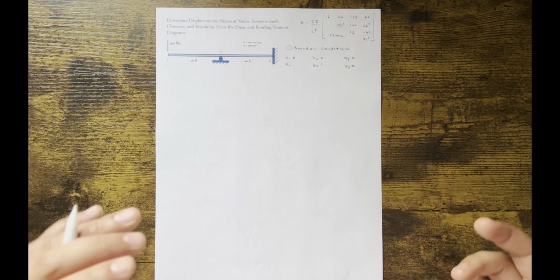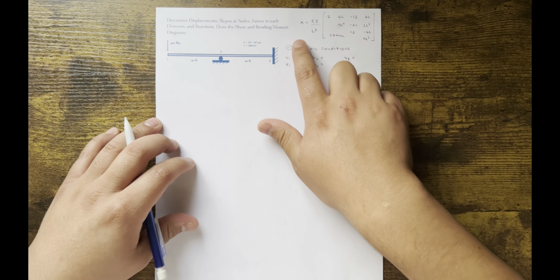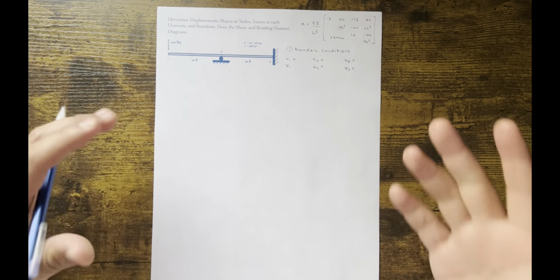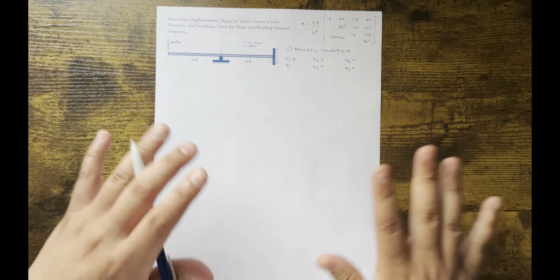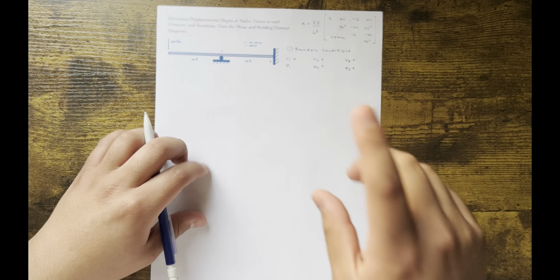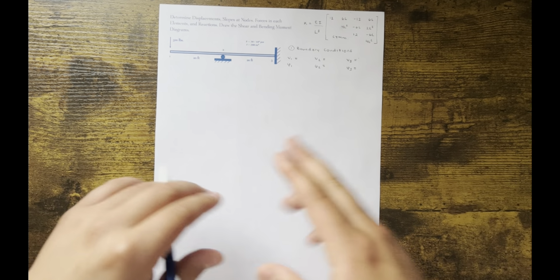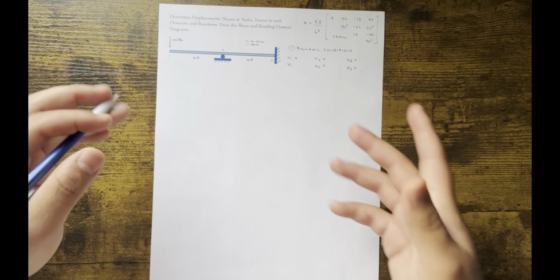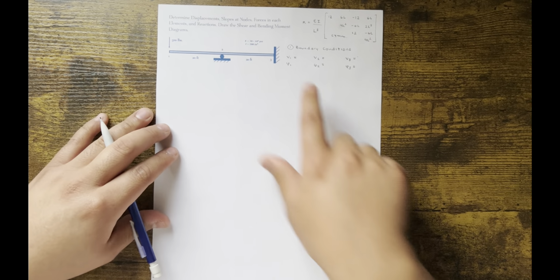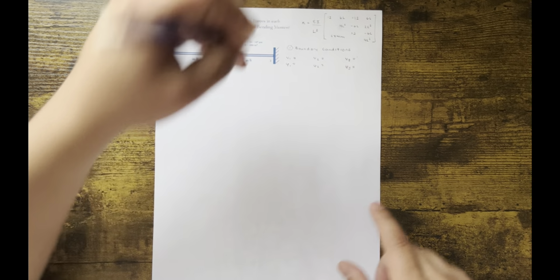All right, guys, so again, you start off with your K, your stiffness matrix. This is a beam, so it has some stiffness, and it's transversely loaded only, no axial effects. So we're going to go ahead and start with the boundary conditions. Again, if you know one, you don't know the other. And I'm talking about V1, Phi1, or F1Y, M1. If you saw my previous videos, you know what I'm talking about.